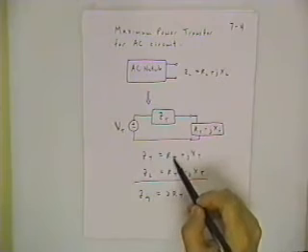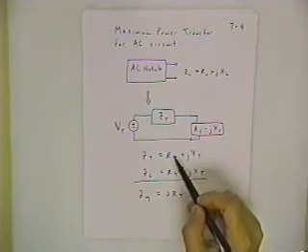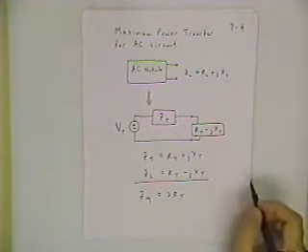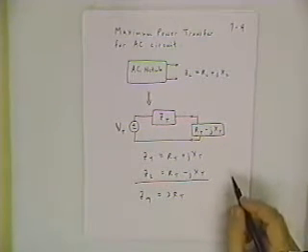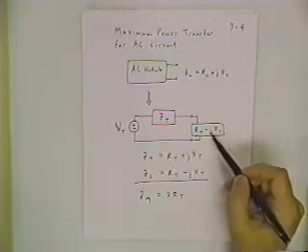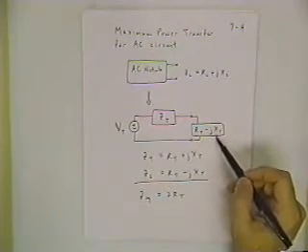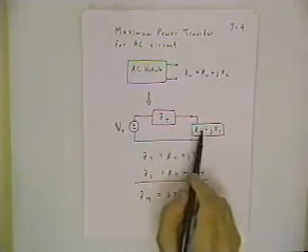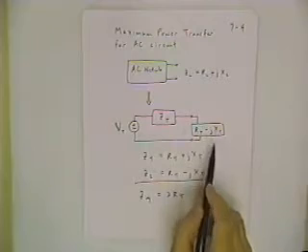It's the resistive part of the power that delivers sound to speakers and delivers force to motors that are turning. Anytime you have a non-zero reactive part, that means you're losing a little bit of your energy to trapped energy in the elements. So to get maximum power transfer, you want to get rid of the X part,